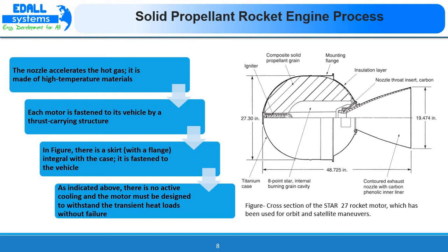And as we have discussed, there is no active cooling and the motor must be designed to withstand the transient heat loads without failure. So the material which is used to make this case is mostly titanium or some alloy metals.